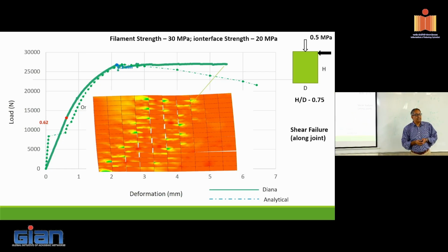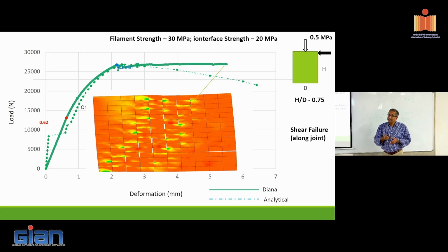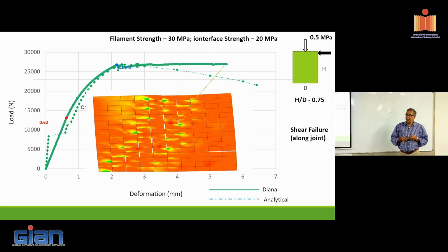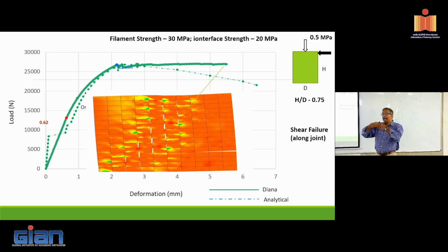So we can now start looking at this mechanics that can be ported from masonry and applied to the case of 3D printed assemblies, right? So here we have all the expertise with the masonry. Just simply apply it, right? And our problem, I believe, is going to be simpler than that of a masonry because we don't have the vertical joints. We only have horizontal joints. But we should be able to characterize those joints properly. What is the shear transfer ability of the joint? That is important, right? And in addition to, of course, the tension and the compressive strength, the tension properties of the interface and the compressive response of the aggregate.